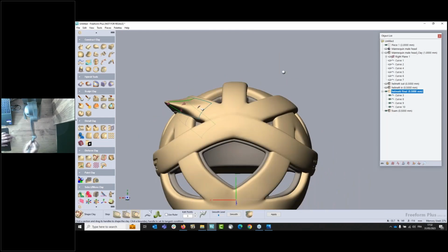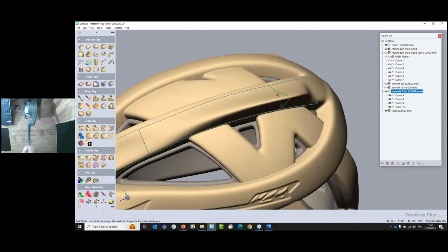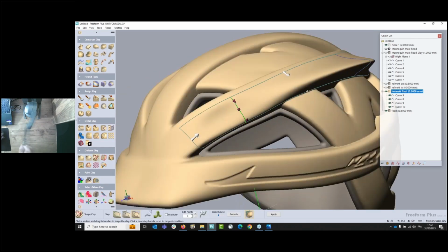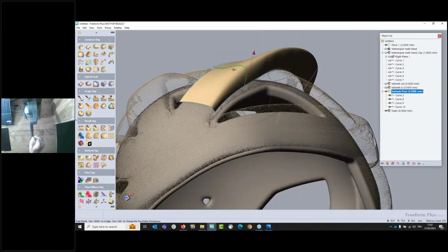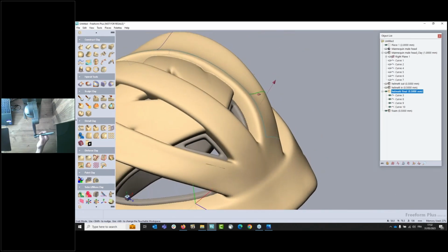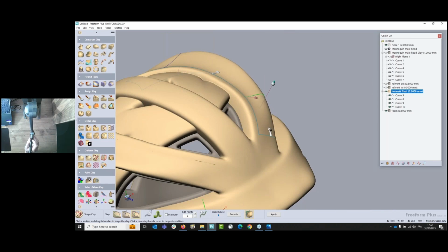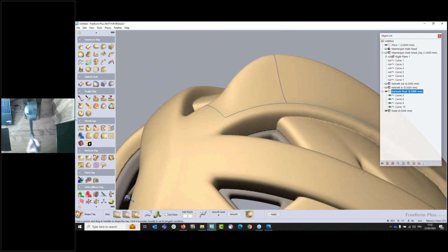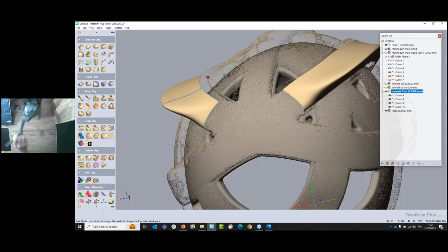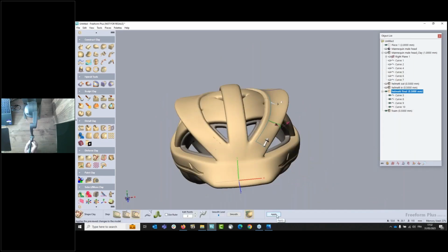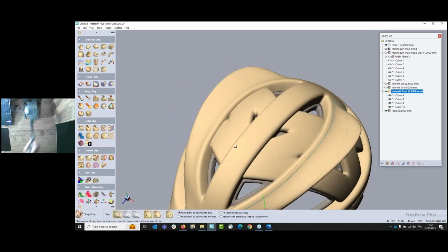And if I want to have a symmetrical preview here, I just have to ask for the interactive mirror shape. It changed this one. I can change the number of points, and I will just increase the tangencies a little just to have something quite regular. Something like this, and it should be good. Okay. Let me apply it. Next thing to do, I will make the same on the top here.